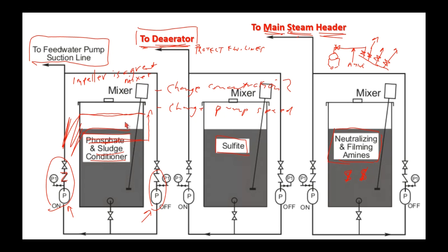But wait a minute, maybe you've added too much chemical. Maybe you've made it too concentrated. Maybe the amount that's written on the tank is for when the tank is completely empty and you completely fill it up, you add so much chemical to it. That's a bit of a problem. There's the whole kind of delay factor, so how much chemical do I add to this tank in order to get the desired effect in the boiler? It's really hard to say because there's a dilution effect of all the stuff that's remaining in the tank, and then you're going to add extra chemical.